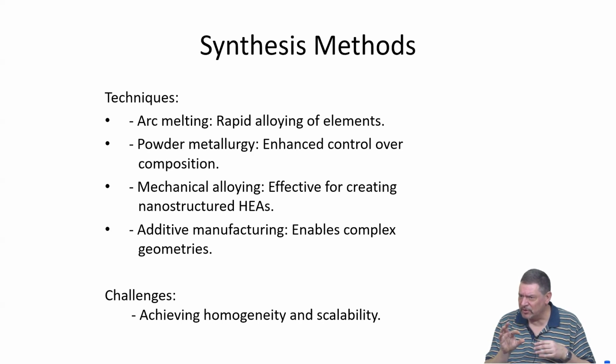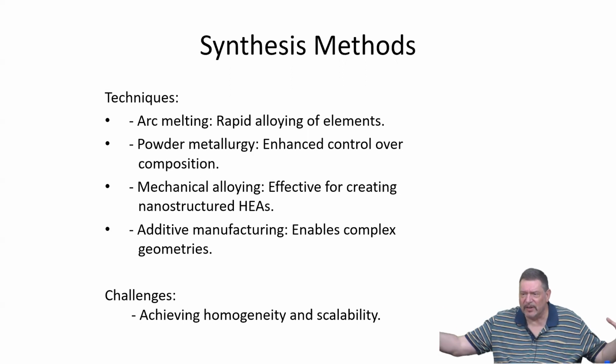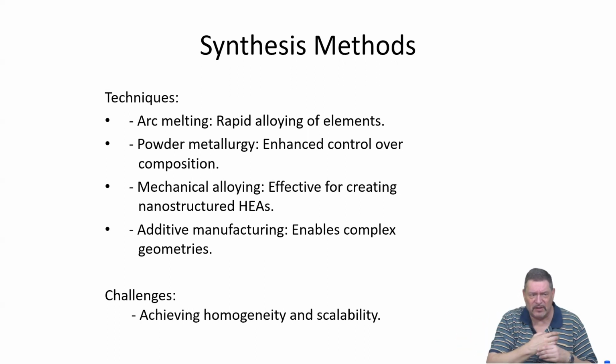Extrusion is something which is similar to that, right? Because you extrude the material and basically you apply a large pressure and the material is in a confinement, so it cannot flow everywhere. It has to go through the extrusion channel. Similar methods exist, but severe plastic deformation means that the amount of deformation is much higher and the pressure, especially the hydrostatic component of the total strain, is much higher, going up to several gigapascals.